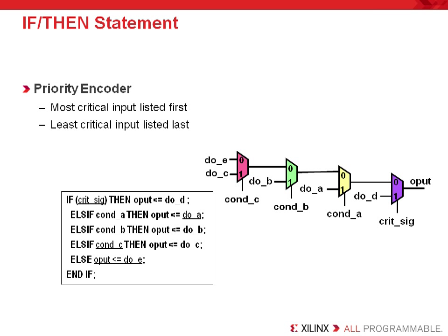The component's construction was all inferred by the synthesis tool when we coded the mux with if-then statements. Note that the order of the inputs to the if-then statements, the most timing critical is listed first, followed by each of the lesser critical signals, and ending with the least critical inputs in the statement.